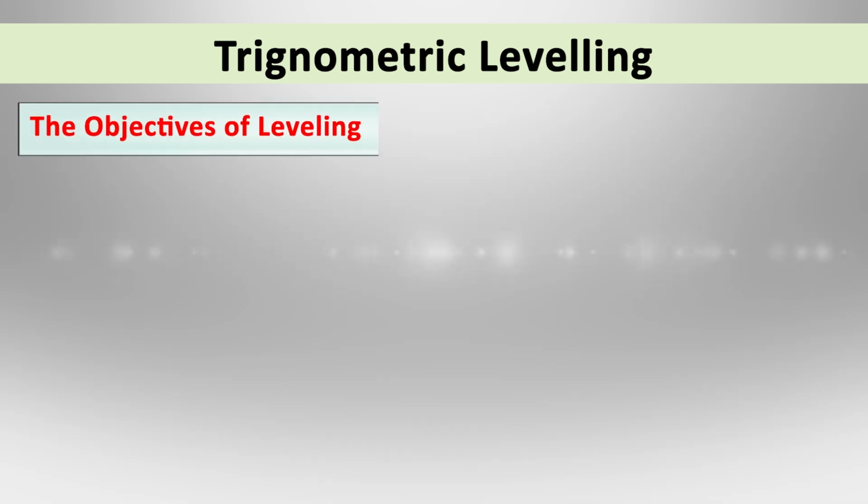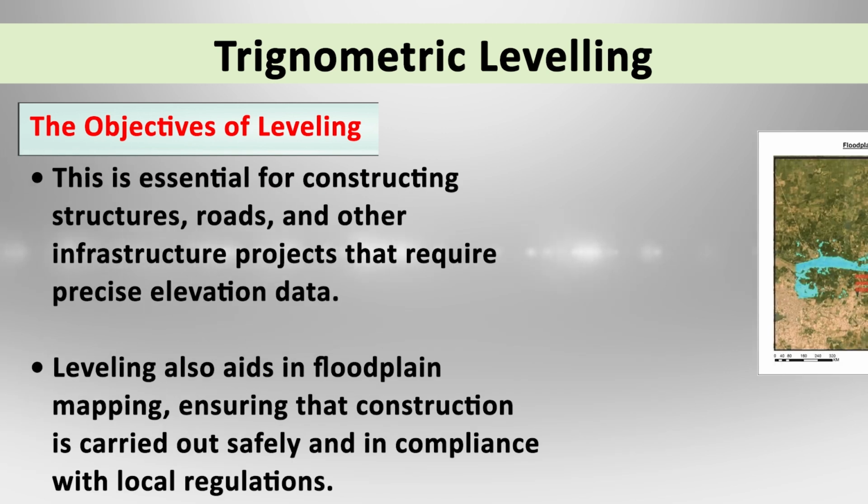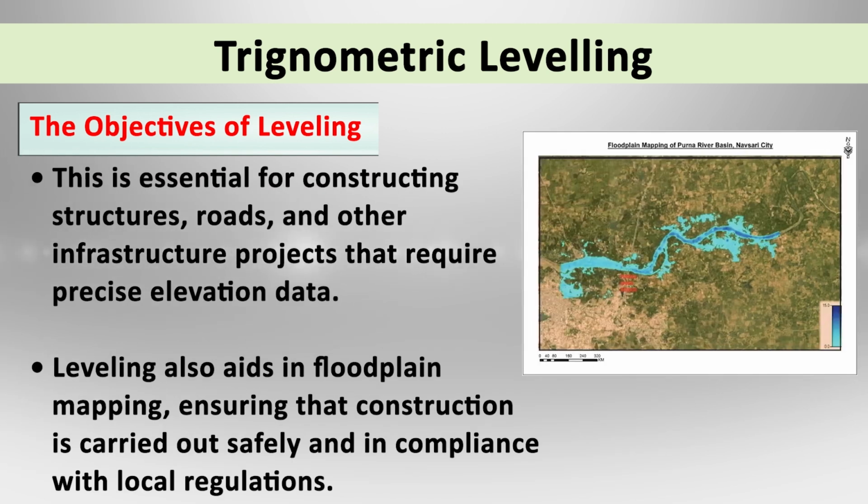The objective of leveling is to establish a reliable reference plane known as the datum, from which height differences are measured. This is essential for construction of roads, structures, and other infrastructure projects that require precise elevation data. Leveling also aids in flood plain mapping, ensuring that construction is carried out safely and in compliance with regulations.